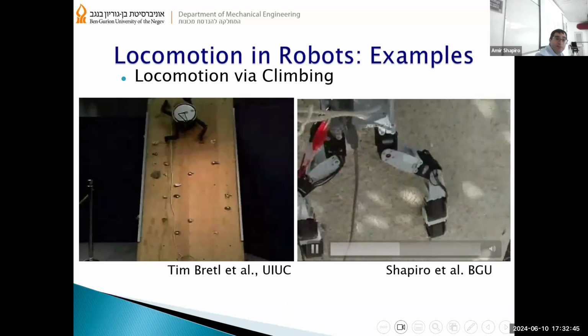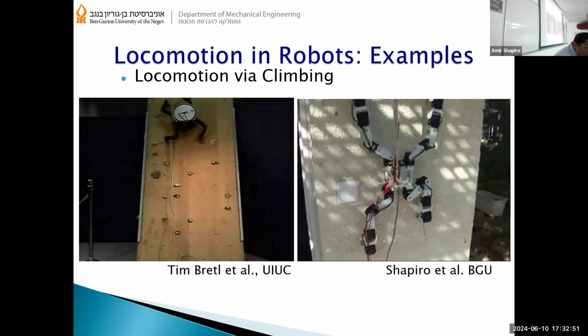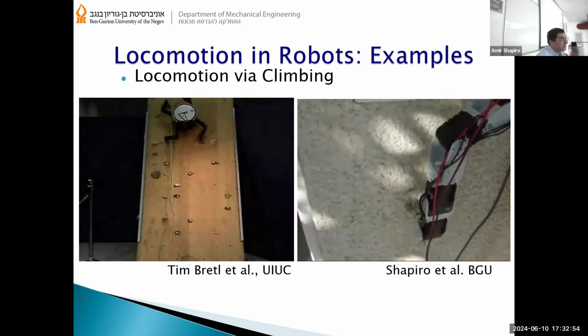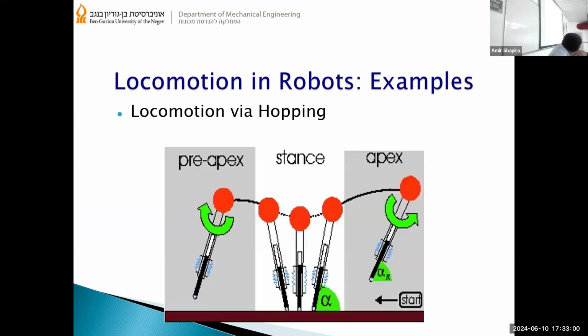And it selects the footpad location in order to maintain balance and advance itself. Another model for locomotion of human-like humanoids is the SLIP model. It can have like a mass with a spring and damper, and does some kind of oscillating motion.